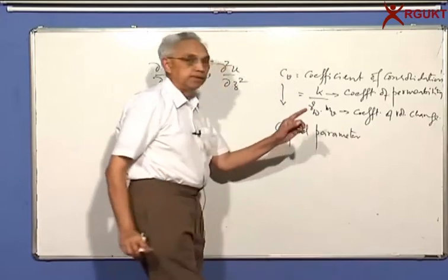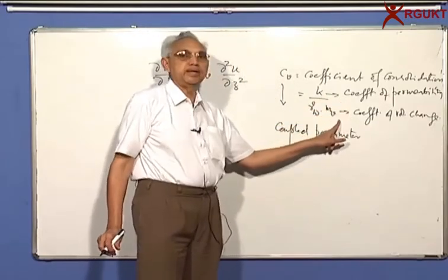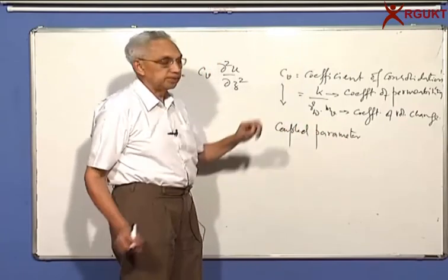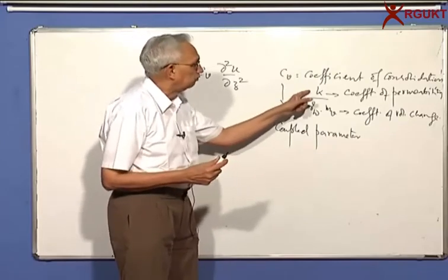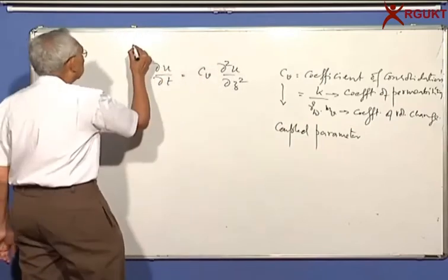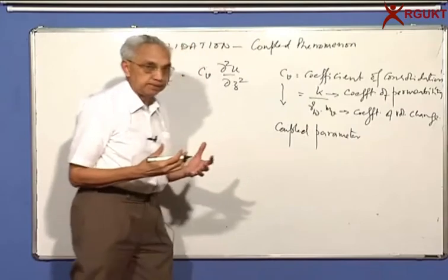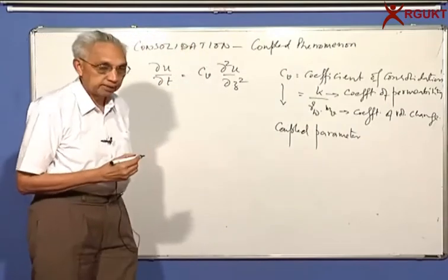It is combining a hydraulic property with a mechanical property, which is nothing but stress-strain relation. So coefficient of consolidation is a reflection of both flow and deformation, and consolidation is called a coupled phenomenon. The deformation occurs after the flow starts or dissipation of pore pressure occurs.